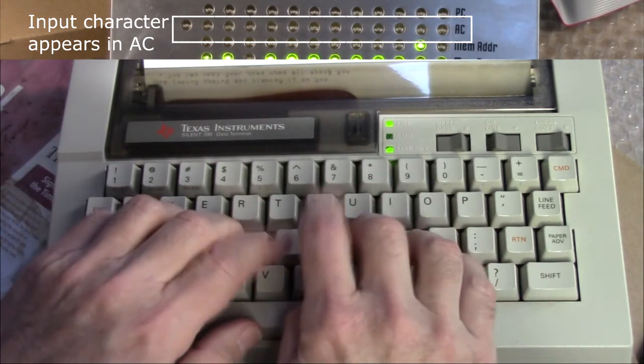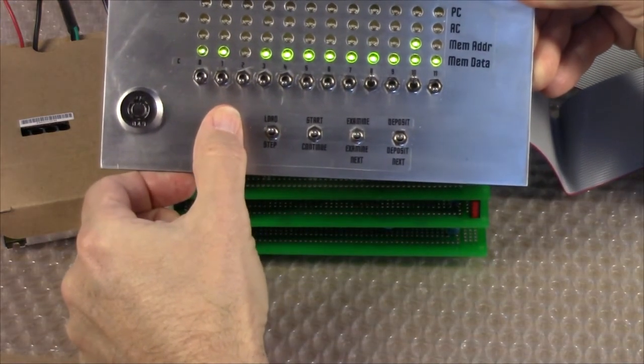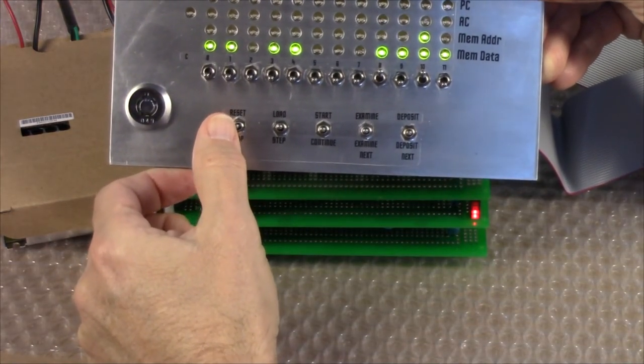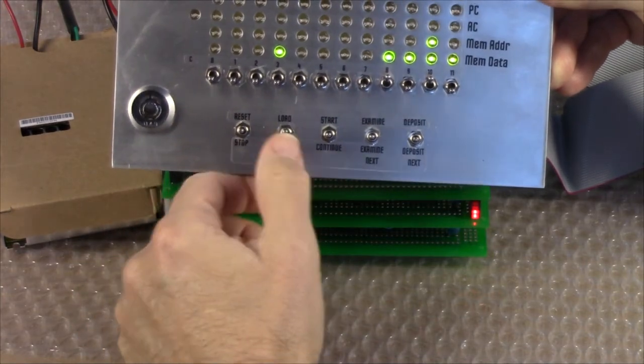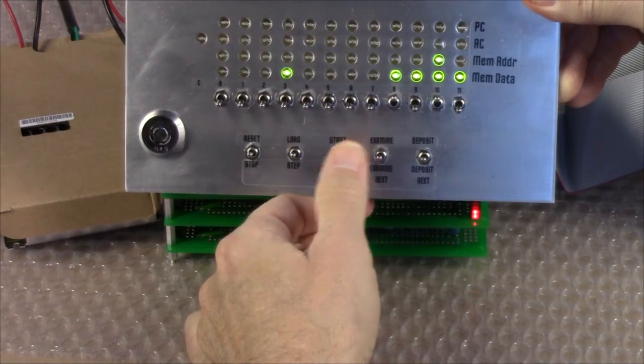So it's gone back to reading the switches. And finally, stop will jump to microcode location FF3, which will display 0011 on the error lights. And you have to reset to get it out of that state.